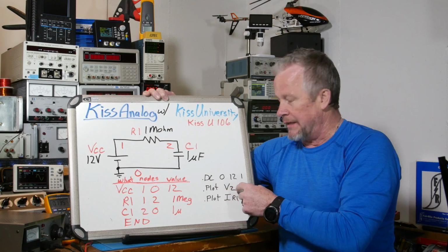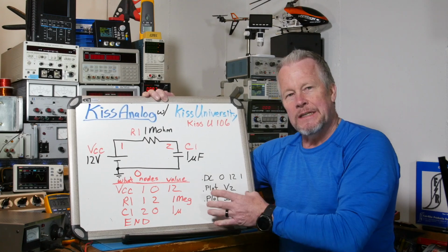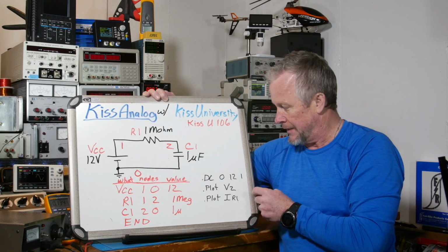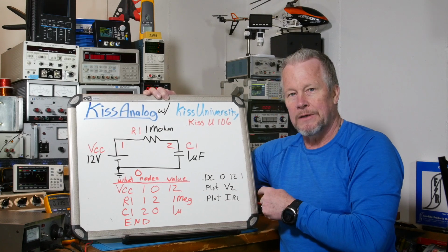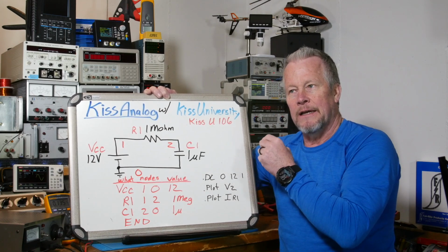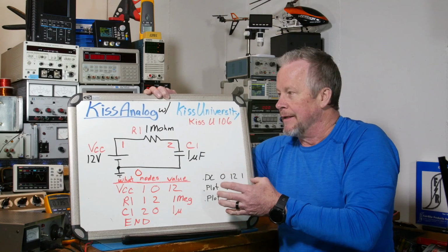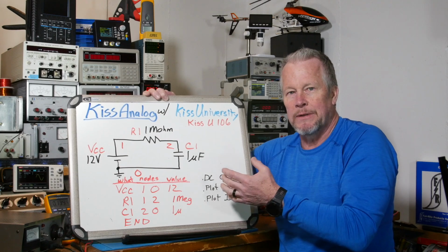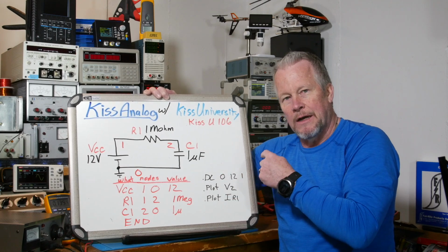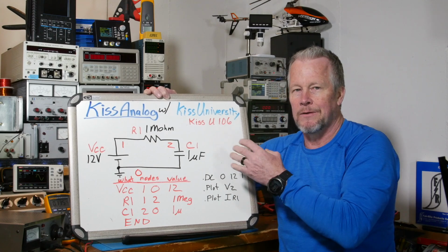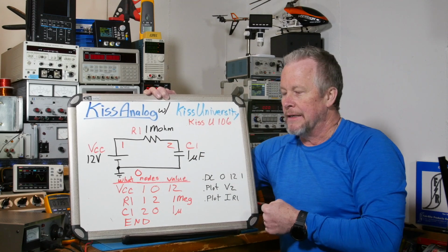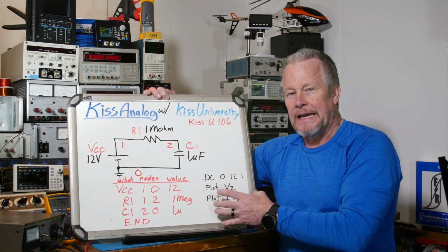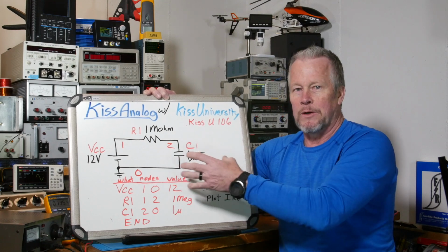And then when you say plot V2, especially let's say we're doing an AC analysis and you want to go from 0 hertz to 100 kilohertz. You'd go 0 hertz to 100 kilohertz. And then you'd say, and how many steps should I take? Should the program just do 0 hertz and 100 kilohertz and plot those 2 points? You'd say, plus, I want 10 points in between. So it'd go 10 points in between. You could say 1,000,000 points, it'd just take a long time. But just understanding that that's what we're going to be looking at when we go look at MicroCap.